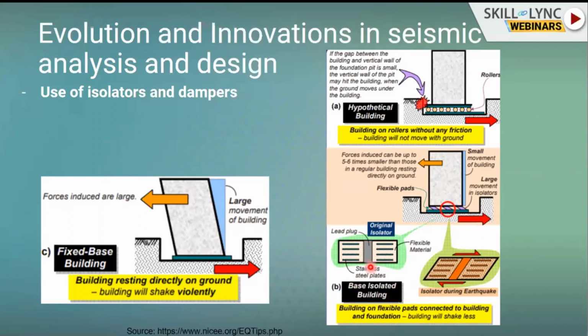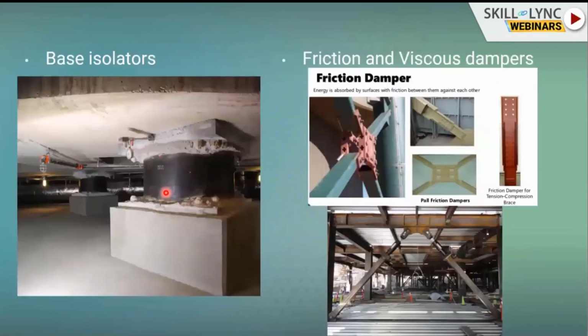You'll have very high density lead or stainless steel plates, kind of rubber plates, inserted at the base of the building that absorb all your force, so the building at the top doesn't suffer any damage. The figure over here shows that base isolation mechanism at the base of the building. Over the top you have your superstructure, and at the base foundation level you provide these rollers or isolation mechanism that isolates your building from the earthquake force.